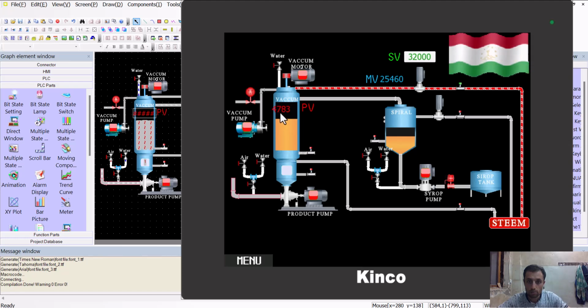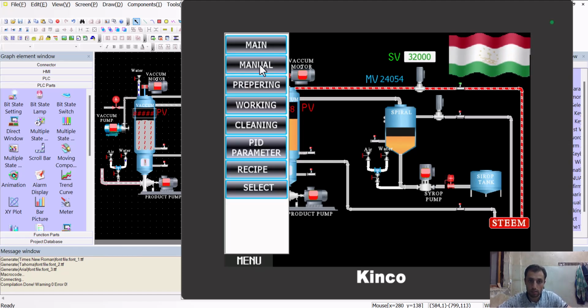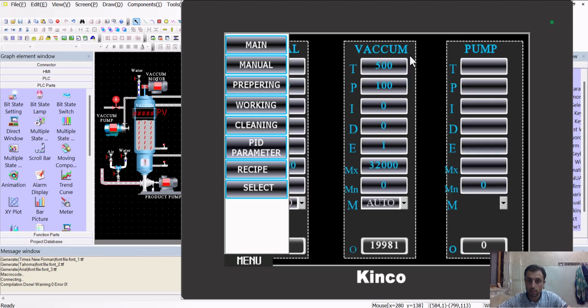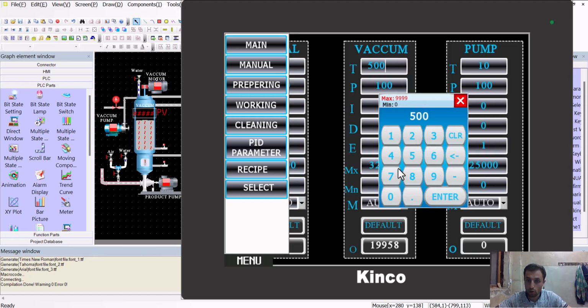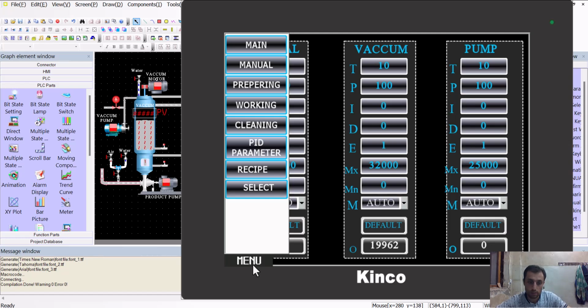I'm changing my input signal, but after a few moments my MV value changes. The differentiation is calculated after that. This is called the sampling time. This TS parameter is the time of the sampling, the scanning of your parameters. I will put one sequence.